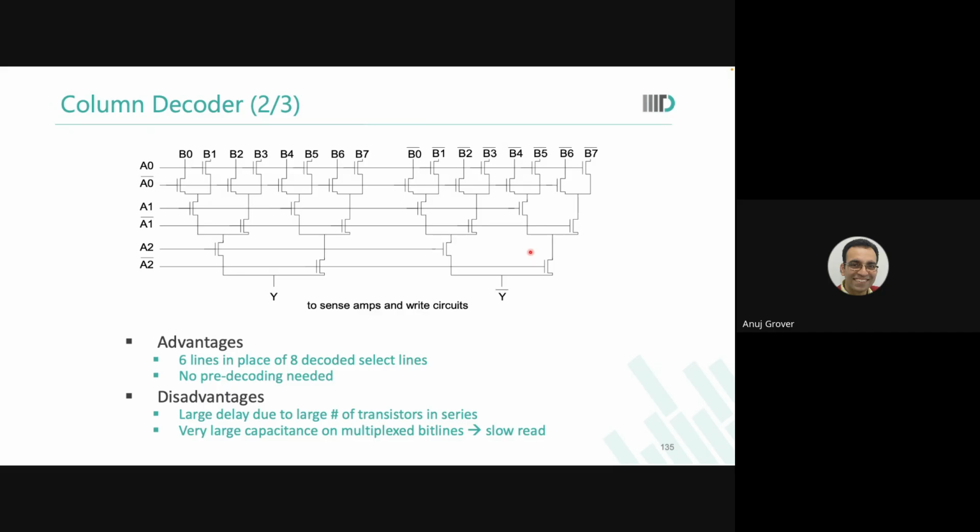If I put the sense amplifier between the 2 levels of muxing, then my sense amplifier can be triggered faster. The disadvantage is that now I need 4 sense amplifiers. Otherwise, I needed 1. So it's a speed versus area trade-off.